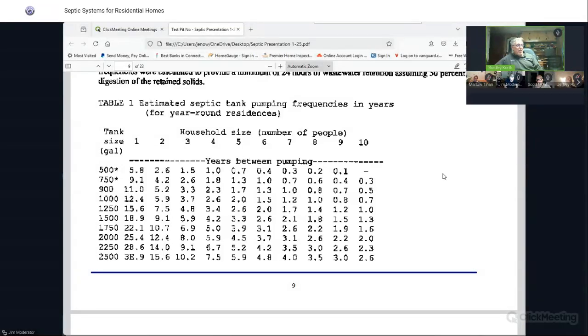So one thing to look for is, has the house been expanded on, and has the septic system not been increased in size because of that exemption? And that's like an automatic exemption as long as you have what they call a code compliant system, which is 100% of the regulations. So you may see a 4-bedroom house that expanded to a 6-bedroom house and they didn't change the size of the septic system. And that could be a problem. It could be, depending on the conditions you have.